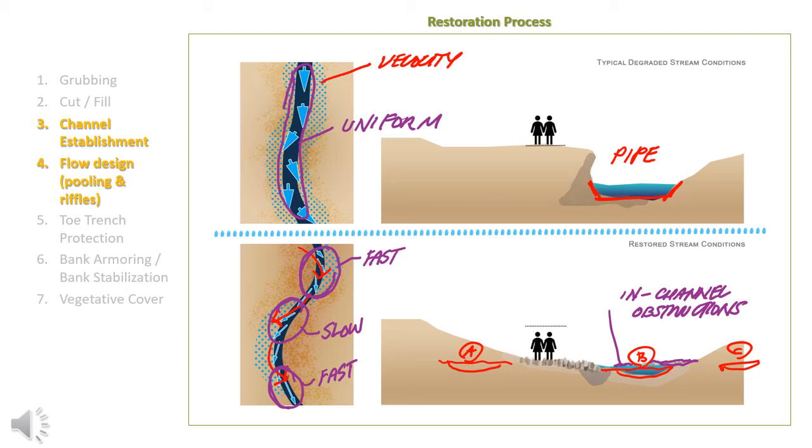The other thing, down at the bottom, as we look at this, what we're really aiming for from a flow design standpoint is that we want fast, slow, fast areas, right? We want some variety that goes along with this. The other thing about the approach to design, a more two-stage ditch, is that, as I show labeled in red as A, B, and C, we want that primary channel to meander through the space over time. We want to allow it to take its natural course through a wider part of the landscape.